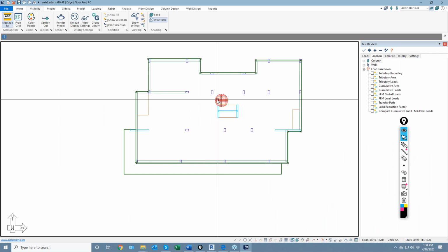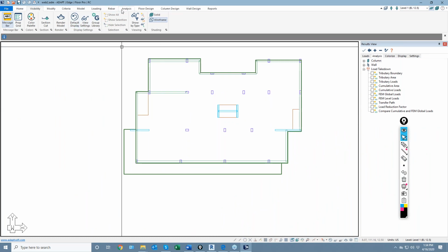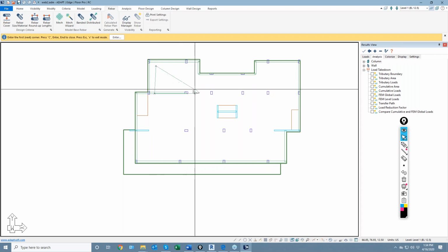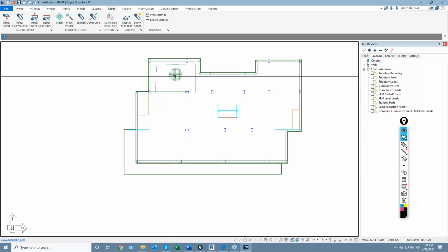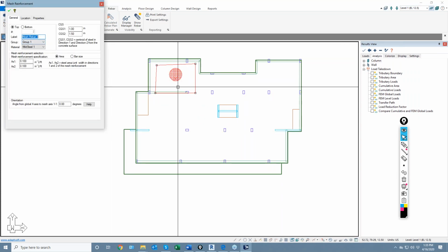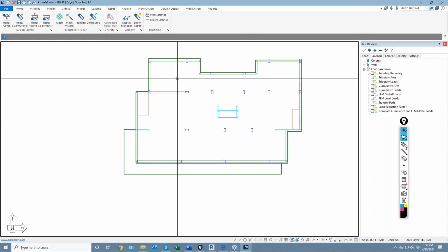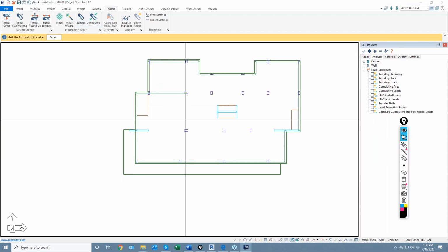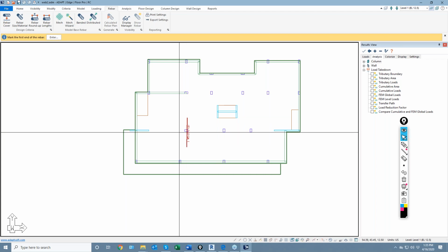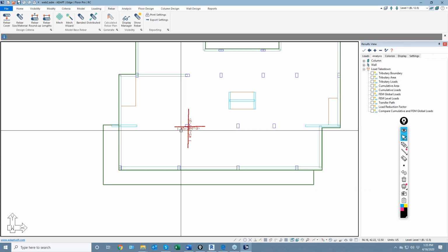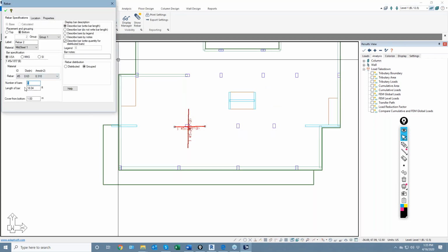You could also just draw that in. You could go back and instead of using the wizard, say, well, I only really have a mesh here, and then go in and specify its properties. But however you add the base reinforcement, it can be through mesh, it can be through banded. Maybe I want top bars. I know we have top bars over our columns, so I'll change that to 4 top bars.